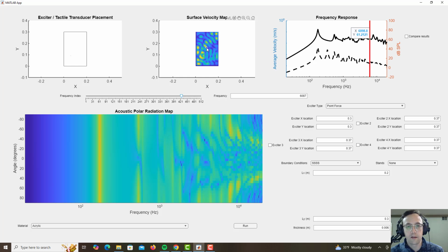Below that coincidence frequency, the wavelength on the panel is shorter than the wavelength in air, and above that frequency, the wavelength on the panel is longer than the wavelength in air. And right at that coincidence frequency, the radiation from the panel is pointing parallel to the surface of the panel. So it goes out at the edges, and it doesn't beam out towards the center.